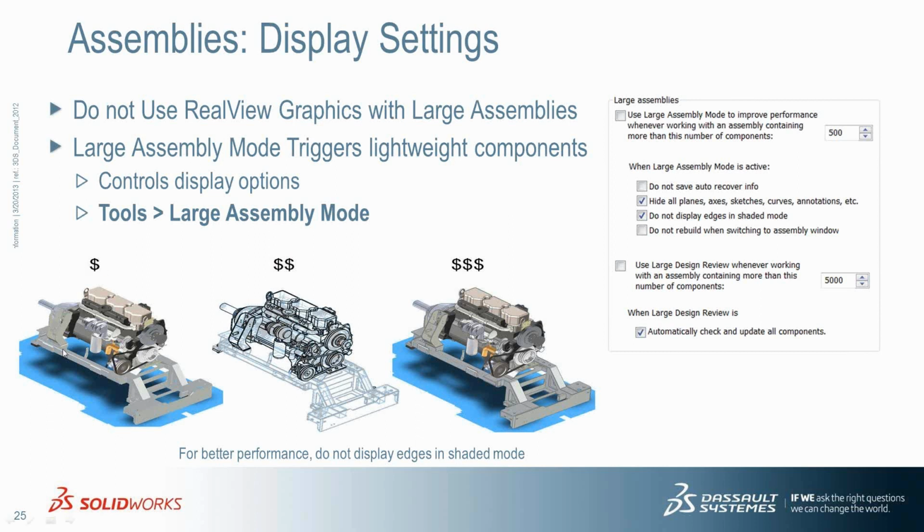The fastest way to view a large assembly is going to be shaded without the edge display, which is going to be my first. The next option up is your hidden line removed. After that, if, and most of us do, use shaded with edges. Shaded with edges is going to give you the most performance hit. Just keep that in mind.